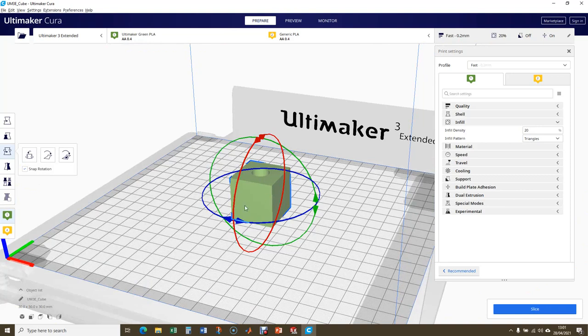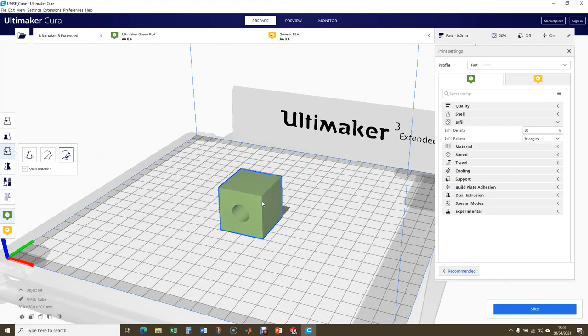Okay. So we'll put that back where we can see it. I could select surfaces as well. Another one I can do is I can select particular surfaces to put horizontal if it didn't come in right. So I can select that one and it will put that horizontal. If I click the top one, it'll put that horizontal. I can click this one, it'll put that on the bottom surface or horizontal. So you can do that if you have a more complicated model and it doesn't come in the right orientation.